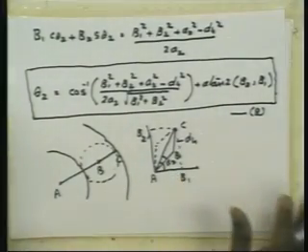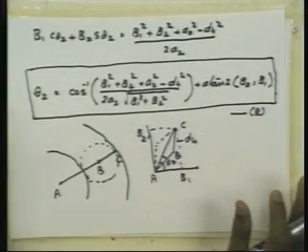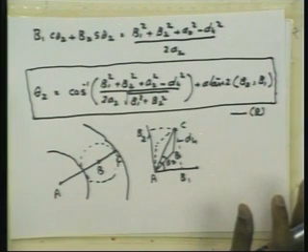So up to now, how many solutions are there for theta 1 and theta 2? Now there are 4 solutions. There are 2 solutions for theta 1, and for each value of theta 1 there are 2 solutions for theta 2. Altogether there are 4 solutions. And now for the final angle theta 3.